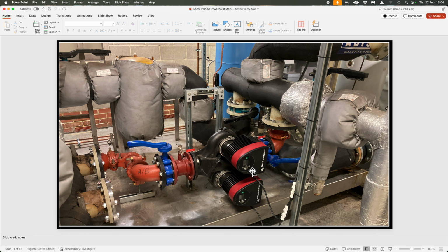And when we replaced these, once we'd done the flow rate and the pressure loss across what we needed, the actual cost of the pumps we went in with came in at just over £10,000. So you can see we don't just have a wastage crisis in energy, we have a wastage crisis in monetary terms as well. Doing an index circuit calculation to get the correct flow rate, what we're trying to do is say the Goldilocks zone is going to be 1 metre per second. That's what we're after. That system now is running much, much better than what it was.